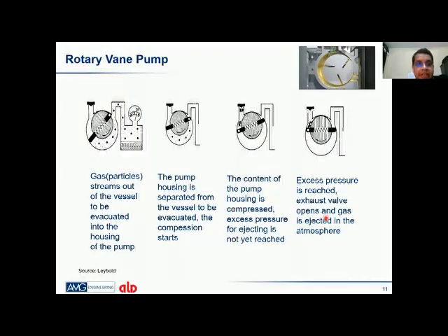So this is a very small picture of a rotary vane pump, which is used for generating a vacuum inside the furnace from atmosphere, from 1000 millibar to 100 millibar. This is our vacuum chamber, and this is a vane pump. It is known as a vane pump because there are two different vanes attached to the rotary part. There is also a spring, because this volume is also changing. I have this video running on top of it, and I'll try to analyze it to show how these vane pumps work.